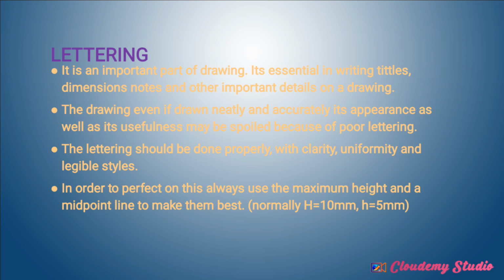In order to perfect this, use a maximum height line and a midpoint line to make them best. Thus I always encourage you in class that before performing any lettering, make sure that you use a height of 10 millimeters as the maximum height. I always label it with capital H. Then we have the small h, the midpoint, at 5 millimeters. If you draw these two lines, they will make your letters stand upright, and at the same time they will be uniform. No letter will be bigger than the other. So that is also an aspect that really needs to be observed.